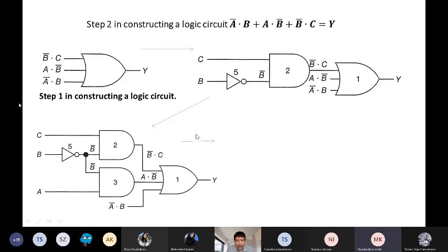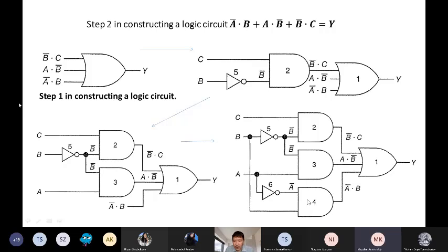Okay, and last, what we should do is give input to the last input of the OR gate. Here it also comes from the AND gate, and you can see that A is inverted. For this reason, here we will connect to the inverter, and it is connected, you can see here, and B is not inverted. So actually, for this expression, here you can construct the circuit that will implement this function. I think it's not difficult, it's clear.